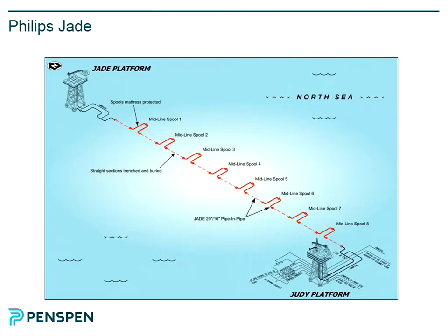They all went into one large buckle rather than lots of individual movements, and that buckle actually failed full bore. So they got full bore rupture basically in their pipeline. So this is kind of an antidote to that problem. It's very expensive. You can imagine a lot of construction, but it's fairly robust from an engineering point of view.